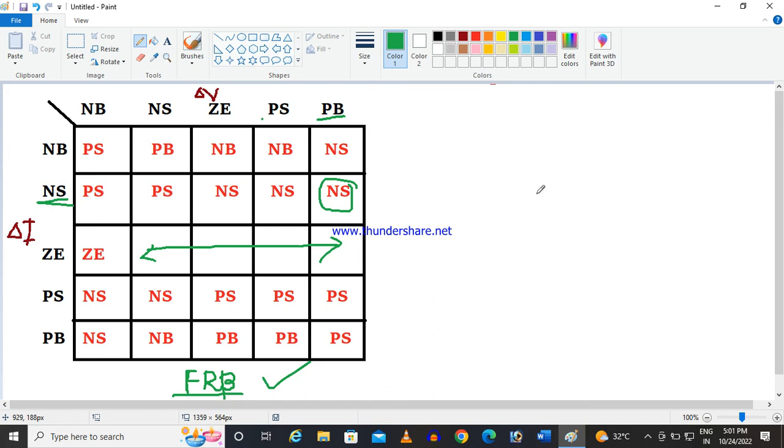For this change of current you also take the difference, that means the present del P by del V and the past del P by del V, which will give the del I. So that is another variable.